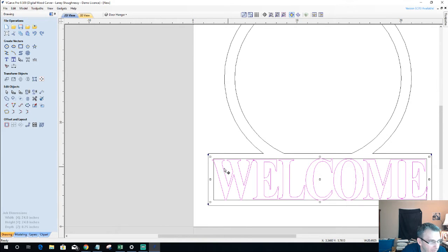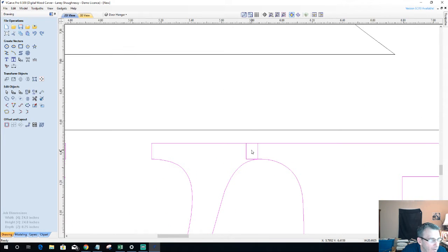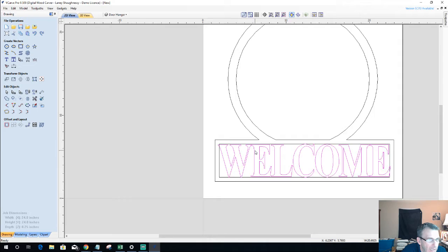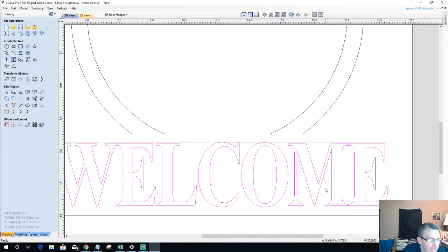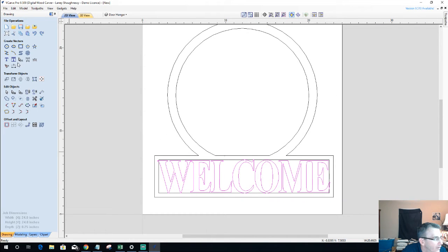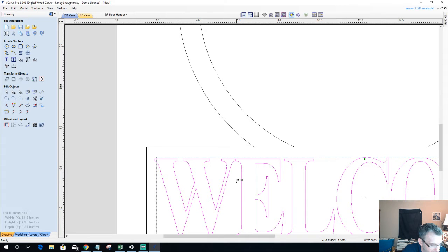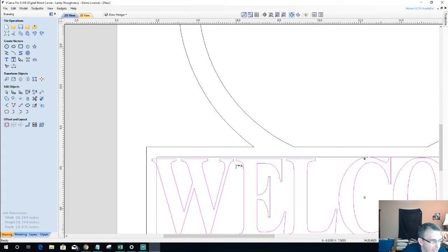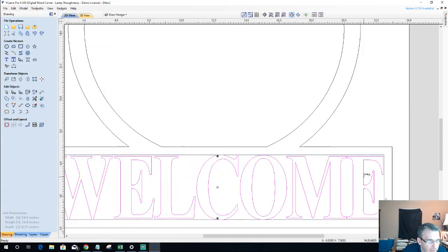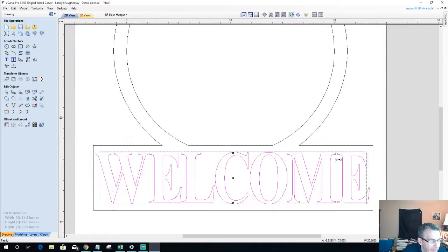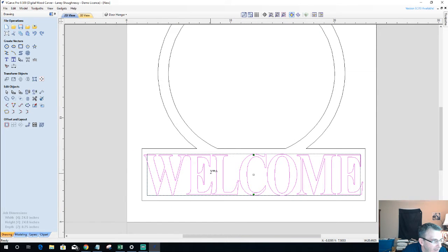I'm in transform mode. I double clicked on it to get into transform mode. And I've got some overlap of my letters here. I'm going to space them out, and then I'm going to end up resizing this. So let's go into our edit text spacing tool. And I'm going to hold down my shift key so I can push that spacing out and just separate that. That was good for that click. And let's come over here and single click that. And a little bit right there.